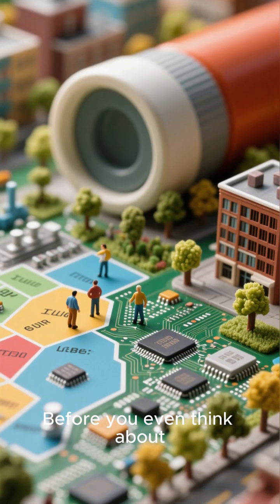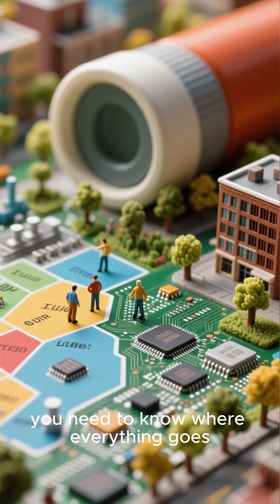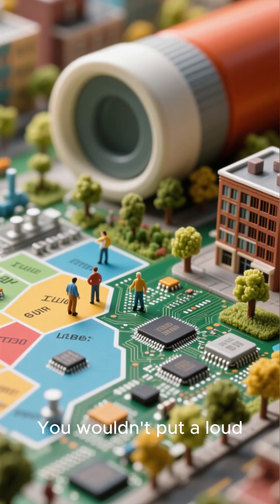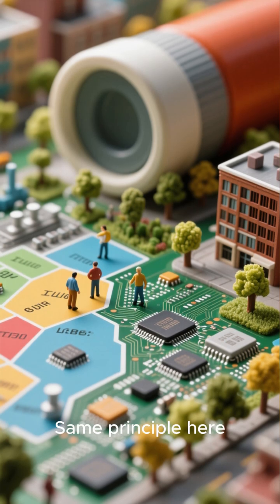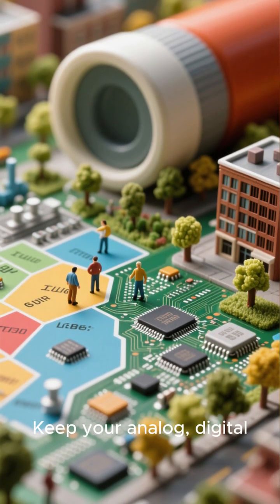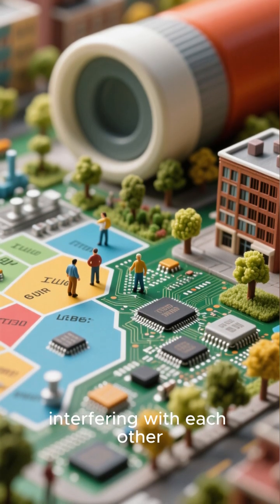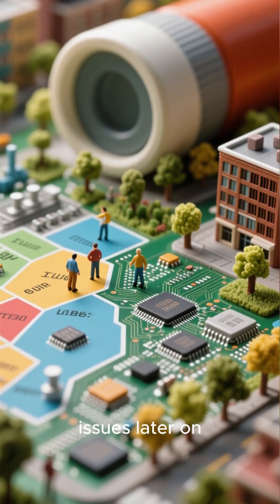Before you even think about drawing a single trace, you need to know where everything goes. Strategic placement is everything. Think of it like planning a city. You wouldn't put a loud factory right next to a library, right? Same principle here. Group your components by function. Keep your analog, digital, and power sections separate to prevent them from interfering with each other. This simple step can save you from a lot of noise issues later on.